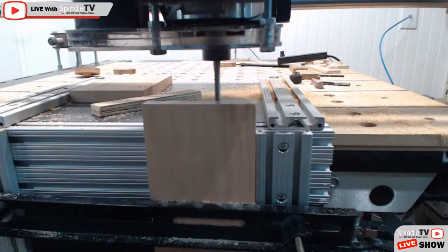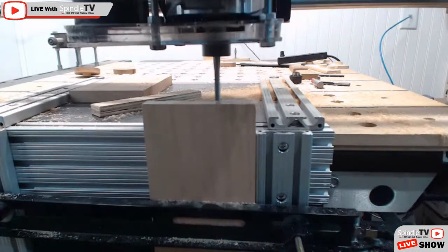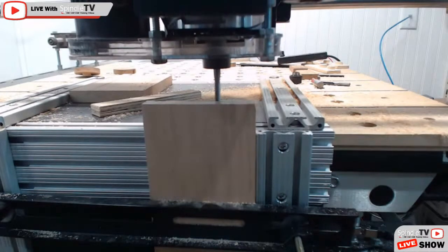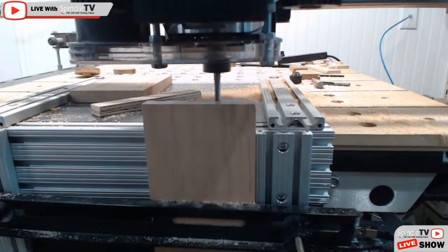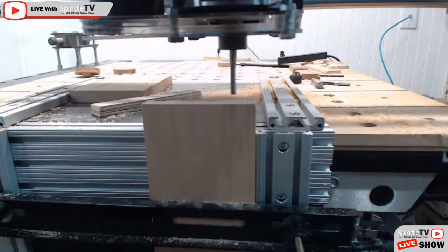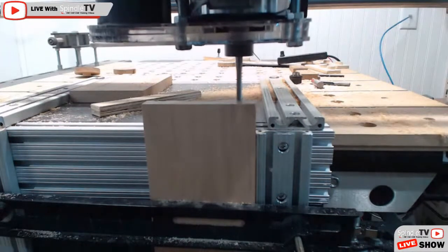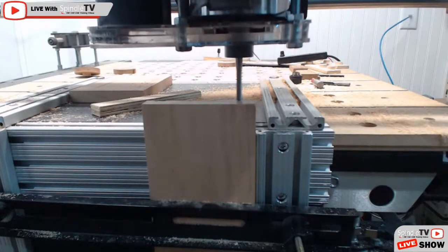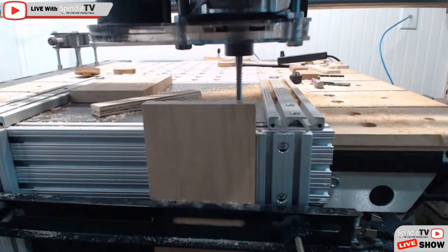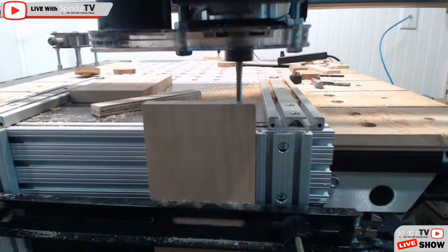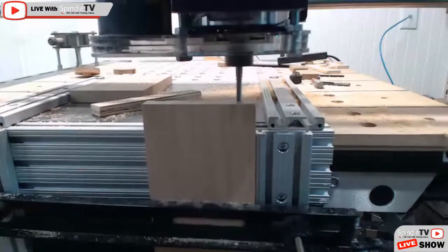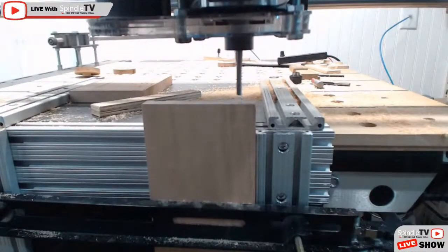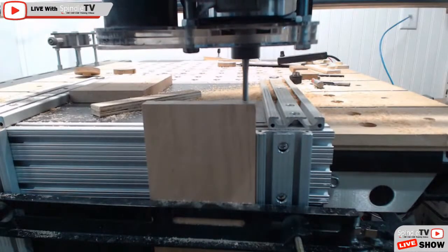So these drilling operations and pocket cuts are used to relieve some of that waste material for the dovetail cutter, because the dovetail cutter is taking the full 0.6875 pass, and that's a big bite. Could risk getting tear out. Oh, Troy, thanks, man. Troy answered that question for Dave as well. All right, cool.